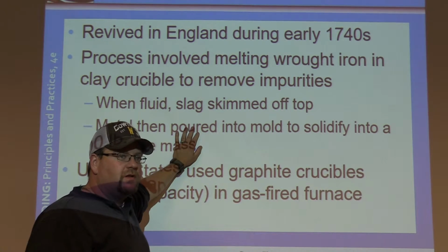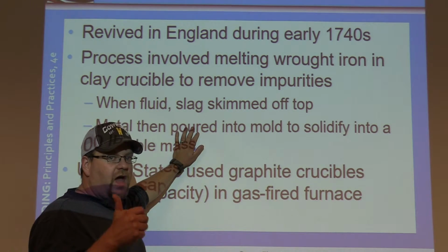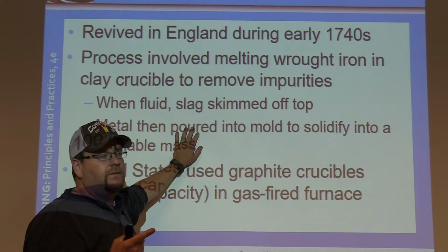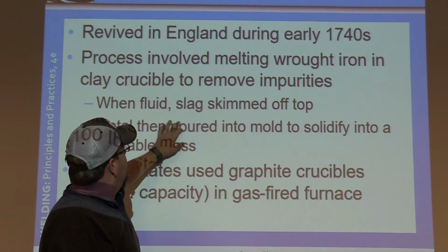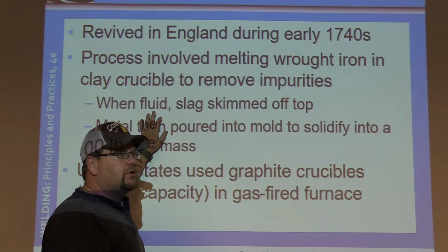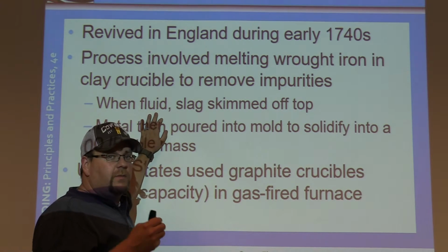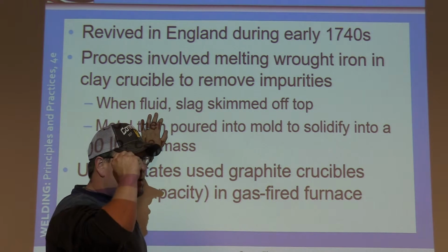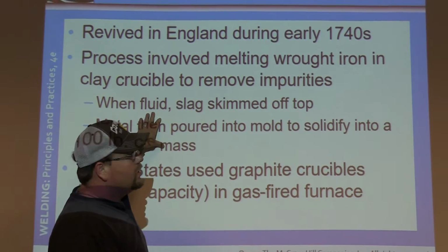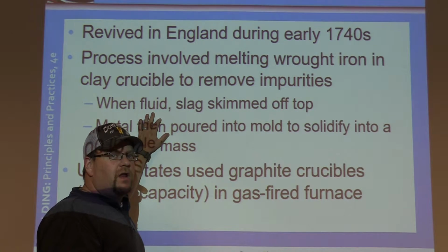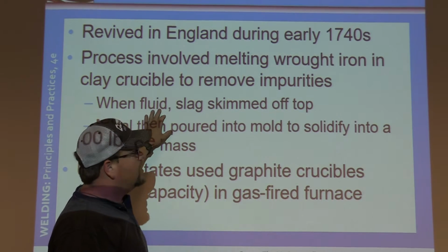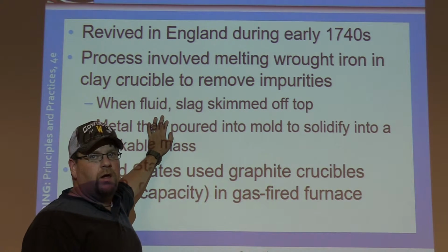The impurities are brought to the surface, whether by gas shielding or by the flux itself. And then also what we found is that at this point is our best chance to add alloying elements to improve qualities as well. Because just like many other things, if we regulate how much we put in, it disperses evenly in a liquid form better than it would in a solid form, okay?